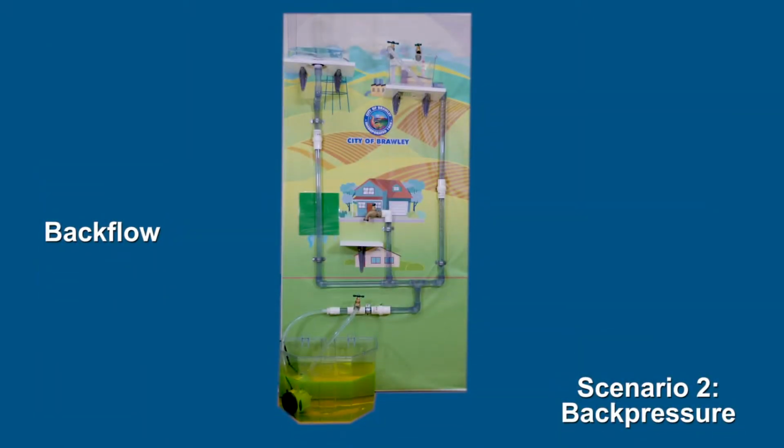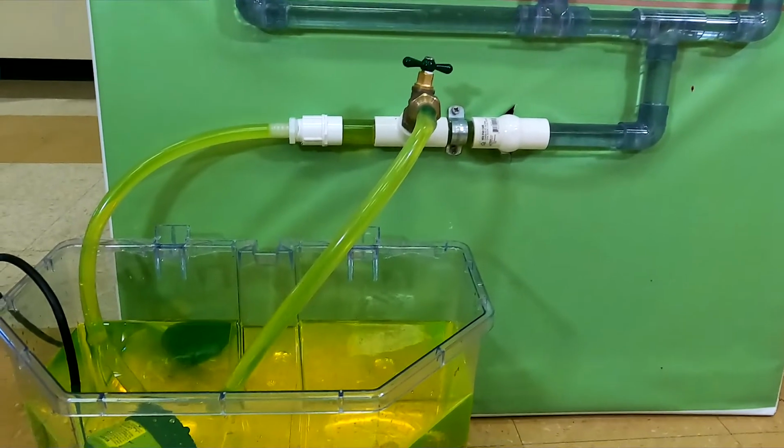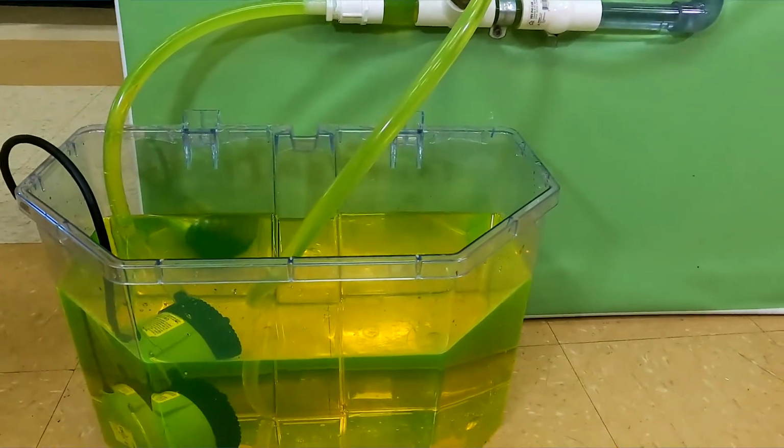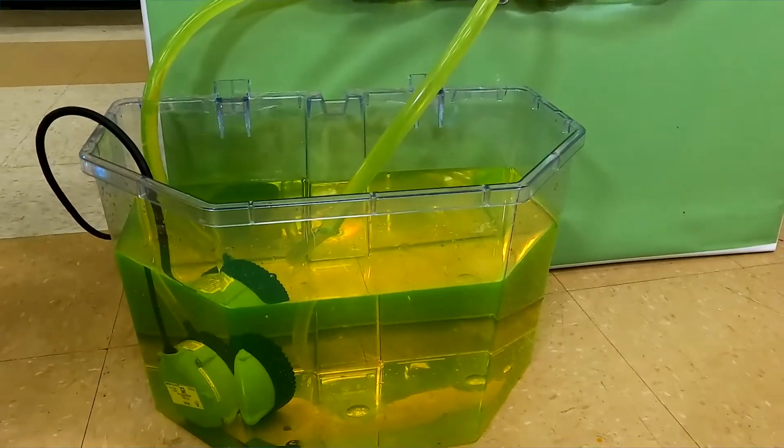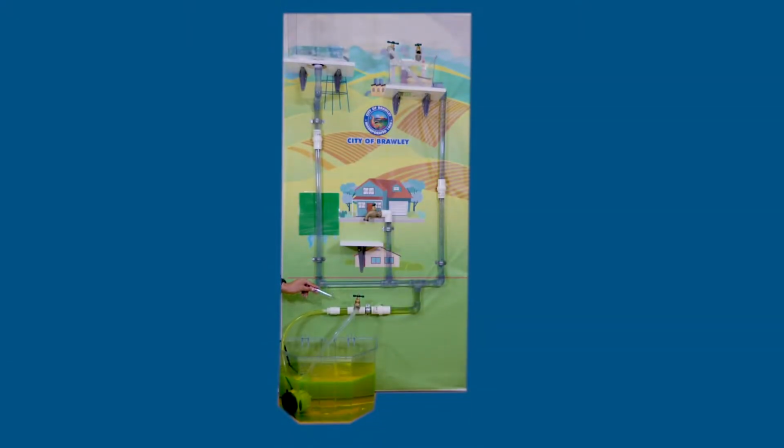The irrigation pump remains connected to raw IID water and begins to pressurize the irrigation lines on the property. However, the homeowner is in a hurry and forgets to turn off his connection to city water supply. Due to the pressure that the pump is working at, the IID water slowly starts to pump back into the city's water distribution network and up to the water tower.